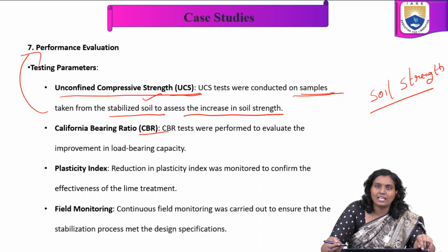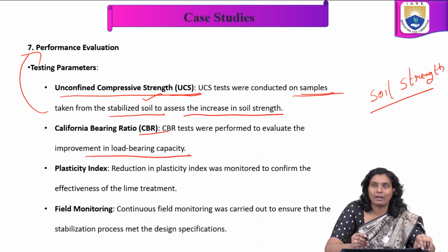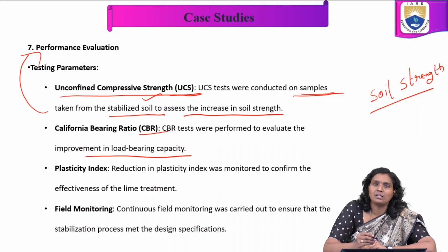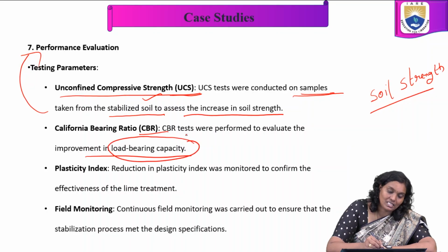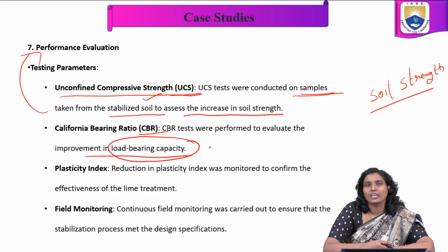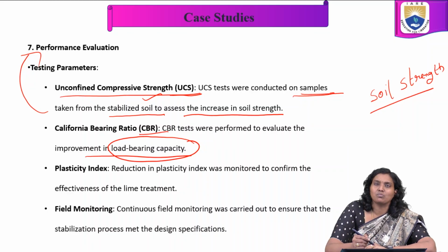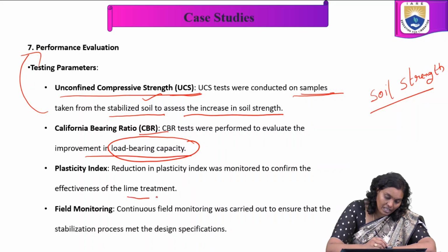The CBR test was performed to evaluate the improvement in load bearing capacity. Once the soil stabilization is done, we perform these tests to evaluate how much improvement there is in the load bearing capacity. And the reduction in plasticity index was monitored to confirm the effectiveness of the lime treatment.